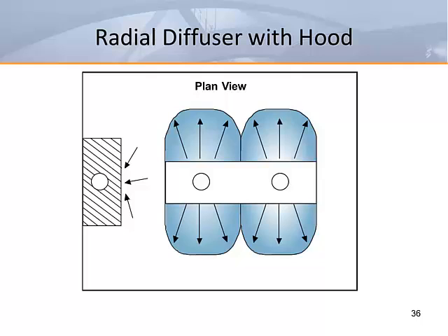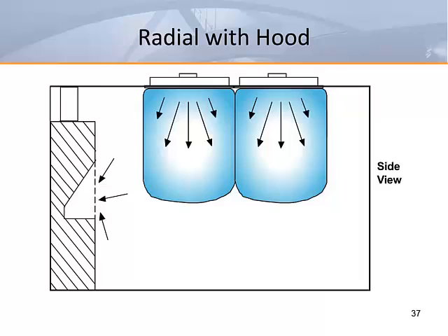One design strategy is to place hoods perpendicular to the diffusers to avoid these high velocity jets. This elevation view shows that it is also necessary to have a vertical air discharge at the end of the diffuser to avoid high velocity jets being directed toward the hood. One of the characteristics of these fourth zone jets is that throw is not affected by continuous length of the air pattern in the same way that it affects standard linear diffusers. The throw for two units mounted end to end is the same as one unit alone.